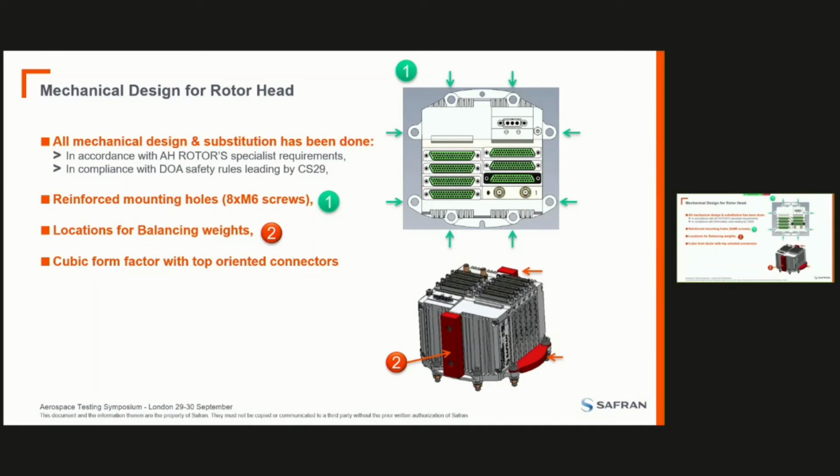So the DAU has been adapted due to this to fit the constraints of rotary parts, meaning that it is shaped nearly like a cylinder, I would say, and also it has some balancing weights that can be mounted and adjusted in order to balance the device perfectly and to minimize the intrusiveness of this equipment mounted on the rotor head.